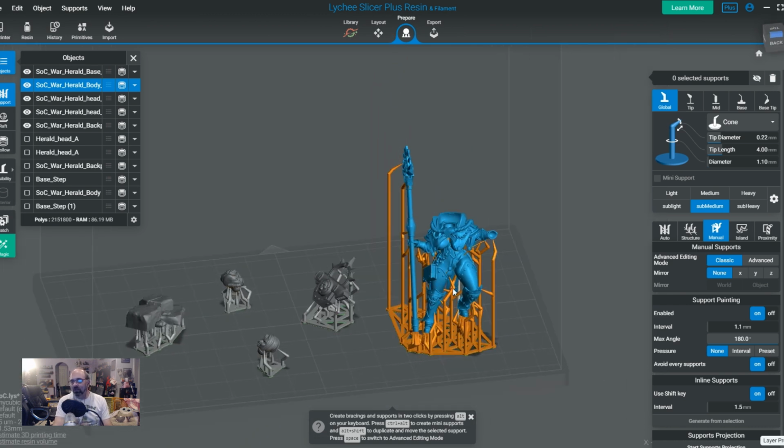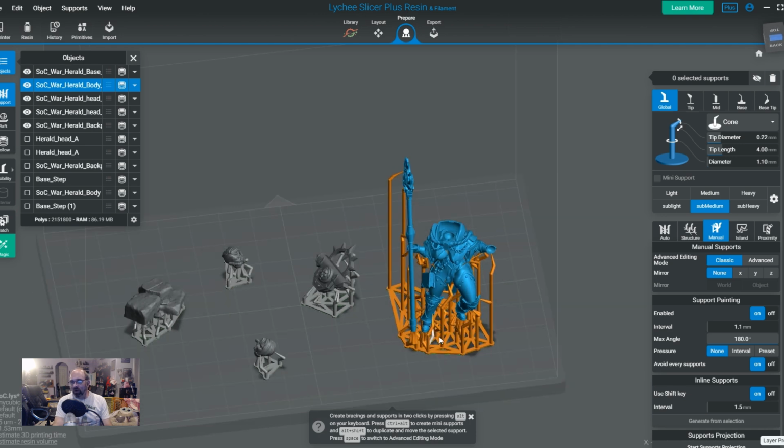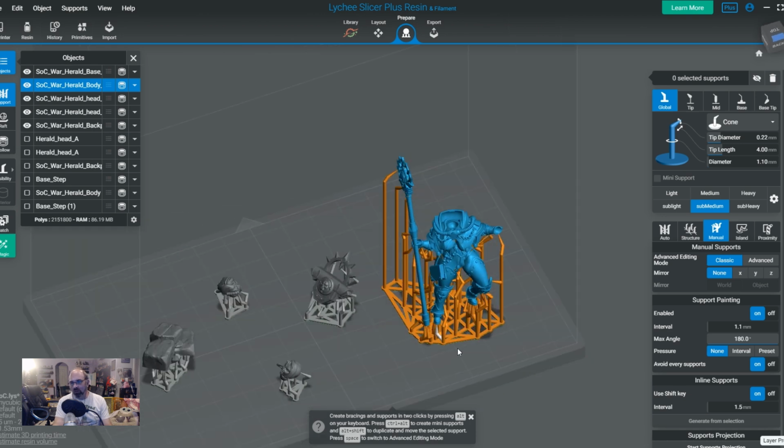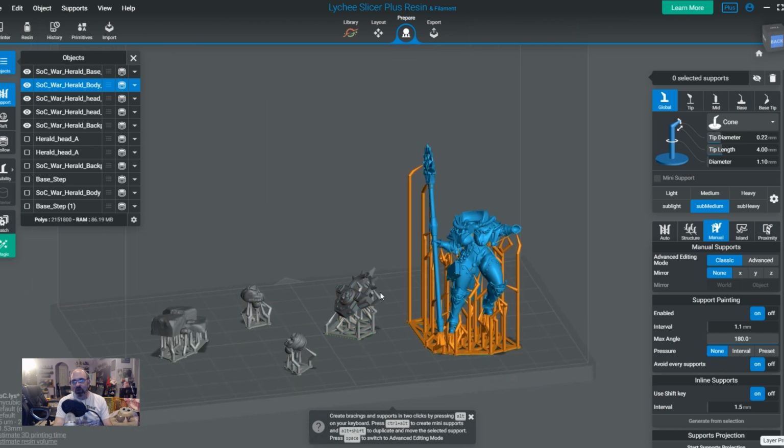If you follow the orientation of the shape, that will help you. Perimeter supporting is a good way to prevent failures or warping or even partial failures. So do keep that in mind the next time you are doing your own support work. And I think that pretty much sums up my list of some of the common stuff that I deal with.